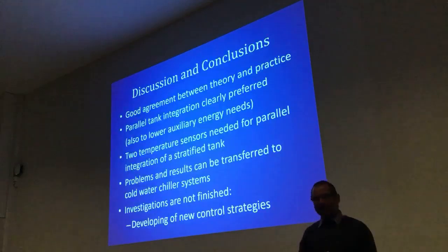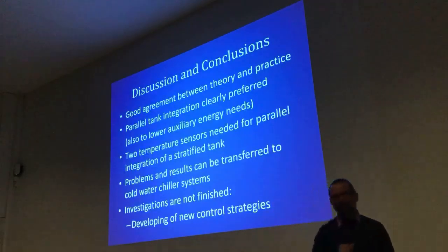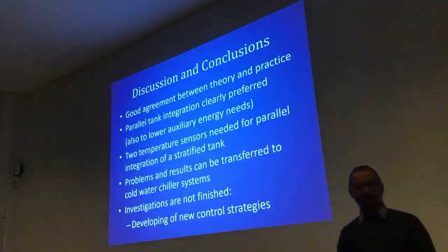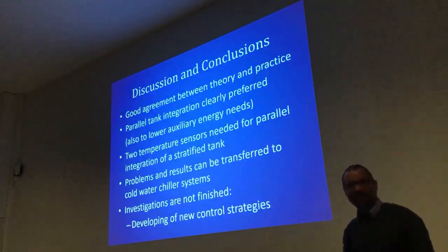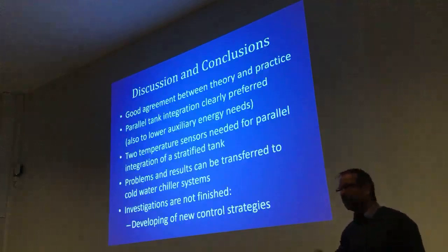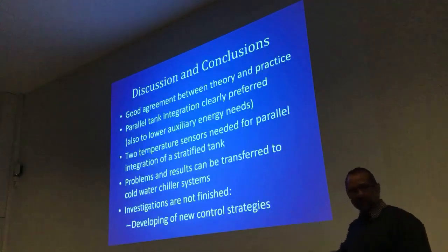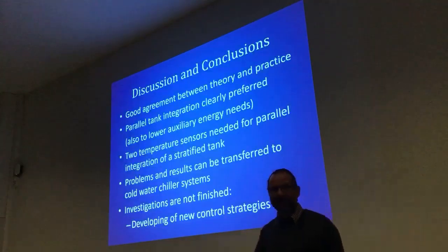Parallel tank integration is operating with a stratified tank, and a stratified tank needs 2 sensors to start and stop charging and discharging. In practice, many of these systems are operated with just one sensor, and that's not working at all.